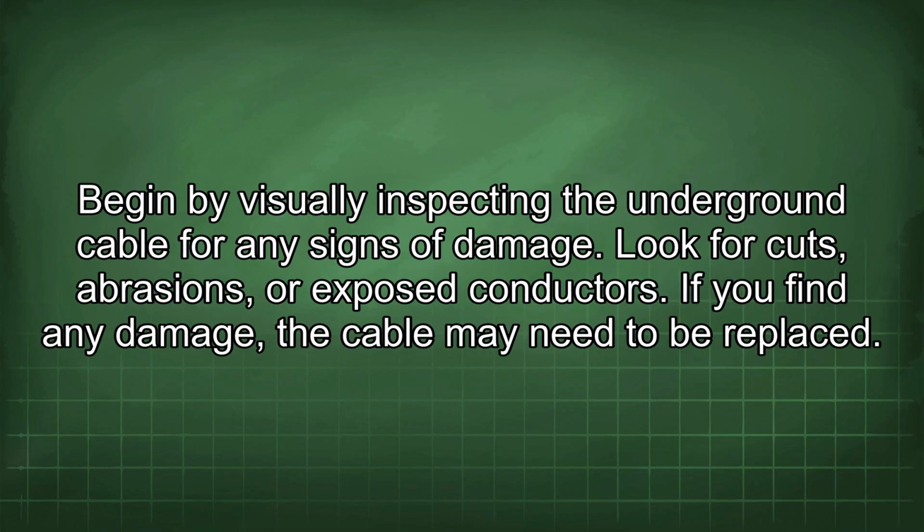Begin by visually inspecting the underground cable for any signs of damage. Look for cuts, abrasions, or exposed conductors. If you find any damage, the cable may need to be replaced.